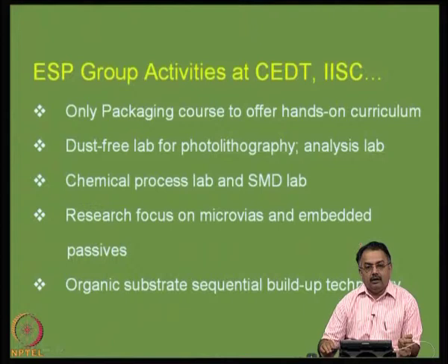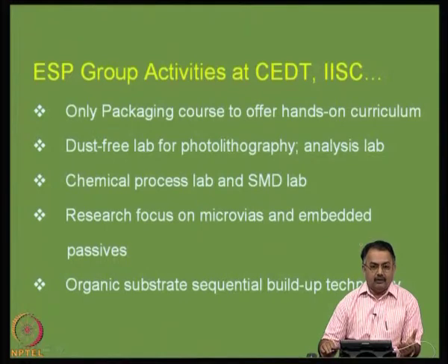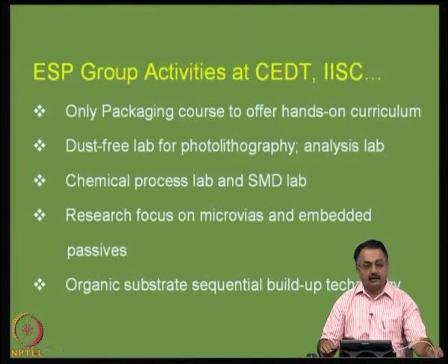Today's handheld products or various other high-end systems tend to prefer to use organic substrates, because organic substrates are very cheap compared to inorganic substrates like ceramics. And during this course, I will also explain how to utilize organic substrate technologies involving sequential build-up technology to produce high density interconnect substrates.